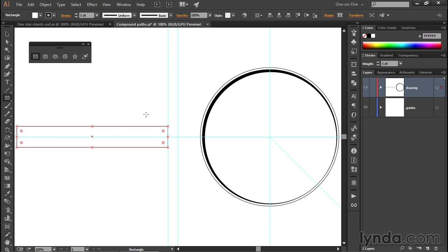You also have that option of spacebar dragging. So let's say I begin a shape right here at the intersection of these two center guides. I'll drag outward, and then I'll press the Alt or Option key on the Mac so that I'm creating the shape from the center out. And I'll watch my heads-up display to read a width of 102 points and a height of 40 points. This is so much easier just to dial in these values, but I'm going to get it right.